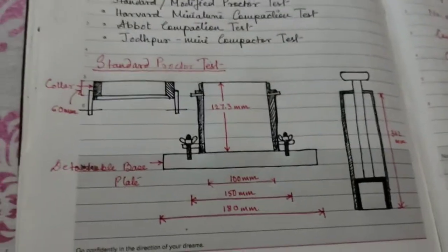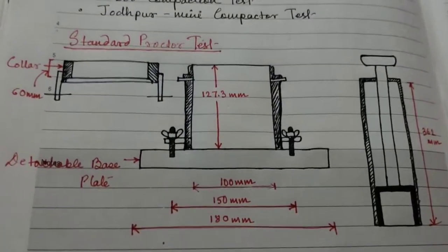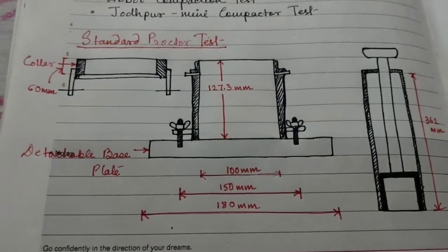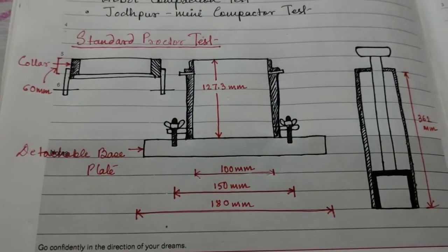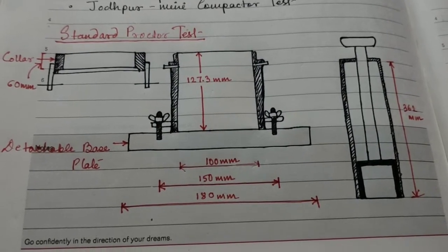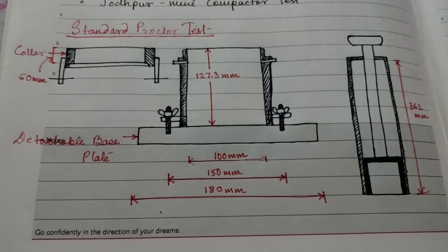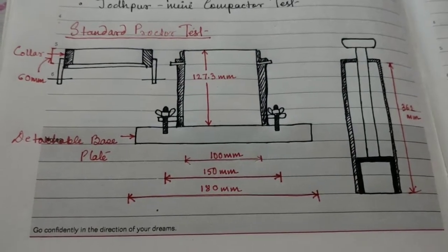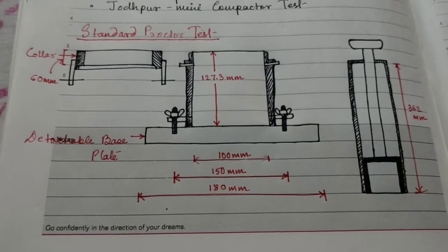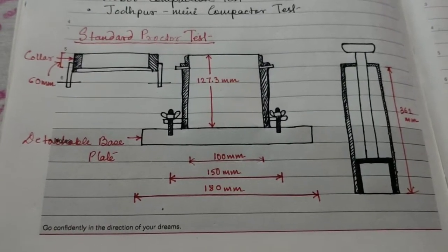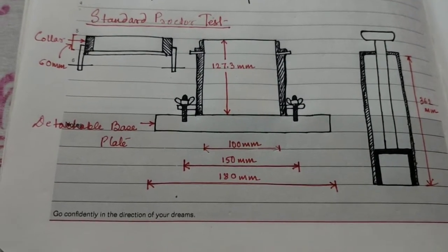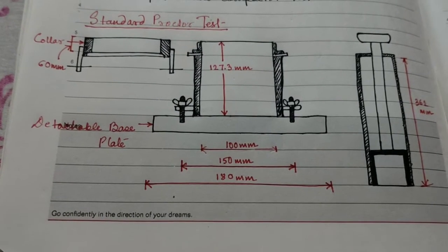You have already gone through the previous soil mechanics unit on how to calculate the water content. As you already know, the water content can be calculated from a simple laboratory experiment, that is the oven dry method, or in the quickest way by the calcium carbide method. But for accuracy, we mainly go for the oven dried method, where a sample is taken, weighed and then placed in an oven for 24 hours.